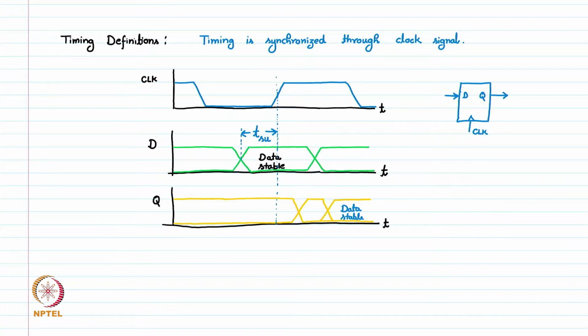And when this rising edge comes and my data will be now propagated inside the D flip flop or this register, then for how long the input should still remain stable so that it is satisfactorily read by the register? So that timing is also important, that is the hold time.